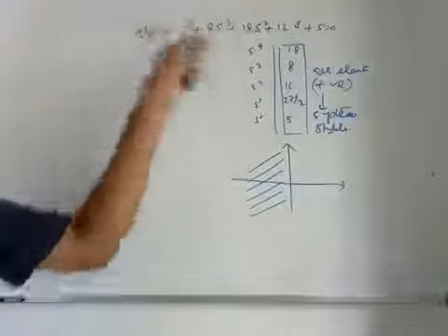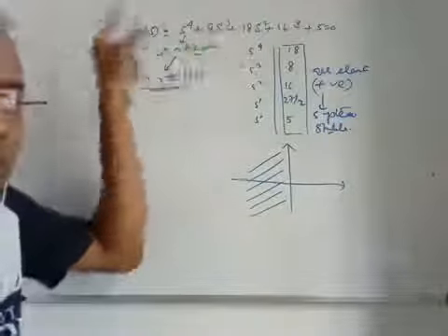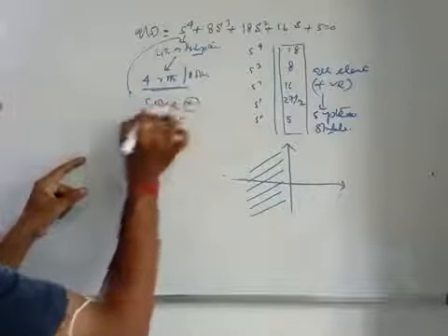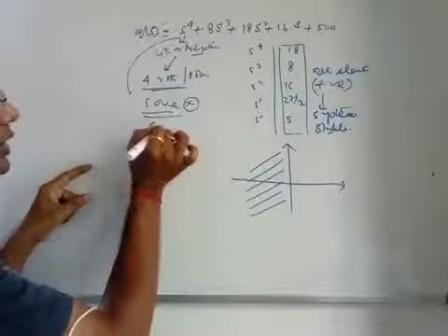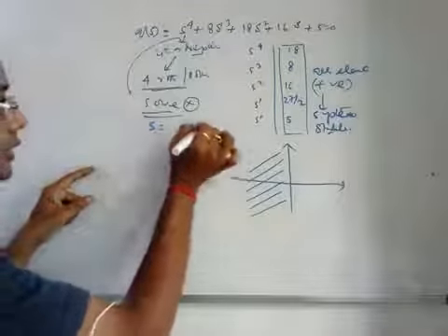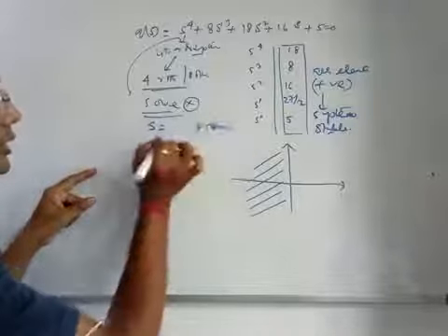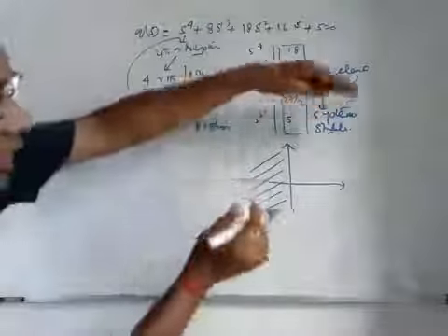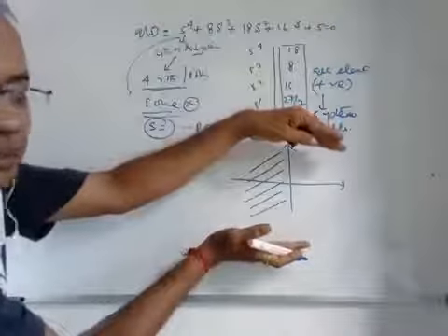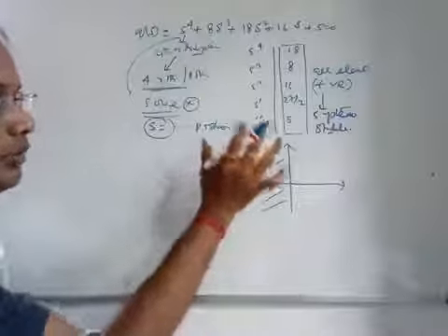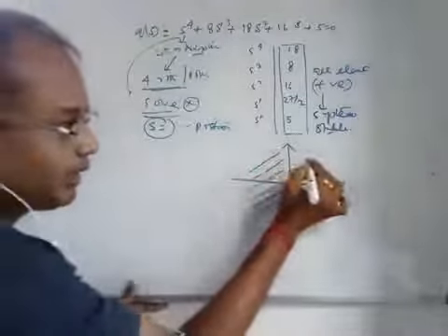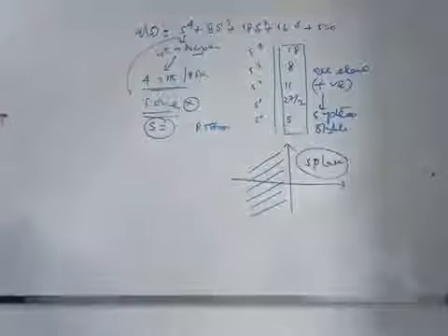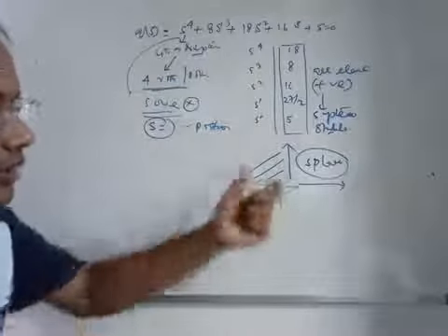Because in this situation, you see, we cannot solve these equations. You cannot solve it. Solve, not possible. So we cannot get the positions. So if you cannot get the positions, then without this Routh array, you cannot get this part. That means it is not possible to find out the root locations on the S plane. If the positions are not possible to find out in the S plane, what does it mean? The stability cannot be analyzed.